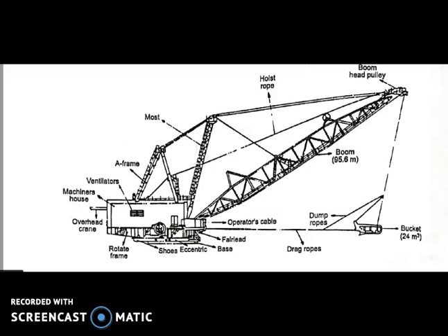Hoist system. The hoist generator delivers power to the two hoist motors. These motors drive the two hoist drums through a gearbox. Two hoist ropes are separately wound on the surface of the drum, while the remaining ends of the rope, after passing over the guide pulley and boom pulley, are connected to the hoist gear of the bucket.